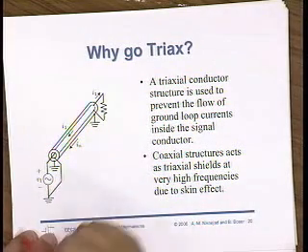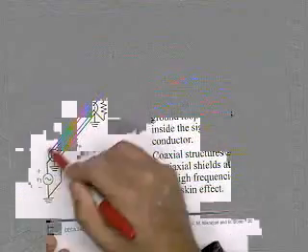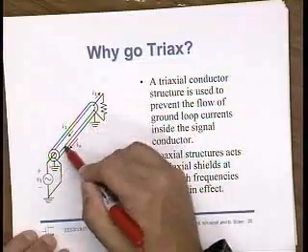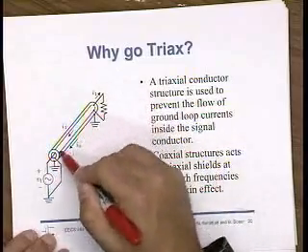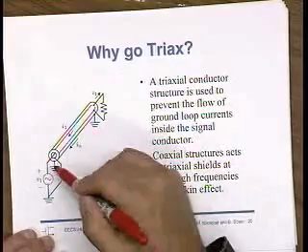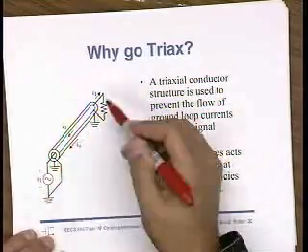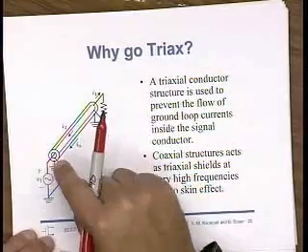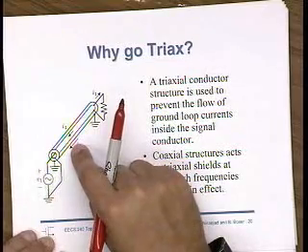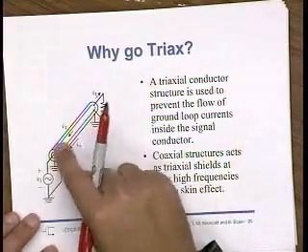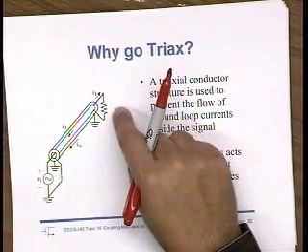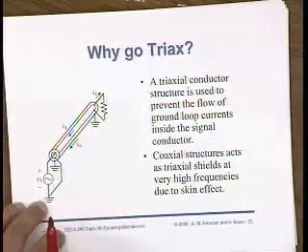And the idea is that the triax current is the big loop. The outer shield forms a big loop where noise currents can flow. The inner conductor here is where our return current flows. That keeps our loop small. So this first loop is a small loop, and that picks up very little noise. This big loop, which is the triax loop, is where our noise current flows. If we didn't have this triax loop, the noise current would flow on our shield. And because the shield has resistance, it would form a parasitic signal, if you will. It would be a noise signal. But because this triax signal now is not connected to our load or to our input of our amplifier, you will not have noise pickup. Okay? That's a little bit of a subtle point. Think about it. Come to office hours if you're having trouble seeing that.